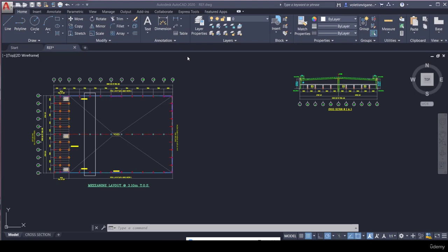Okay, so what is your doubt? My doubt is the property we assign, like we assign the depth of web as 350, suppose. So it will be at the center of the column in STAAD. Yeah, so the same property should be at the face of the column in AutoCAD. The depth of web. Yes, in STAAD, the depth of web will be at center. Yes, I got your doubt. If the depth in AutoCAD we provide at the flange. No problem, I understood your doubt.